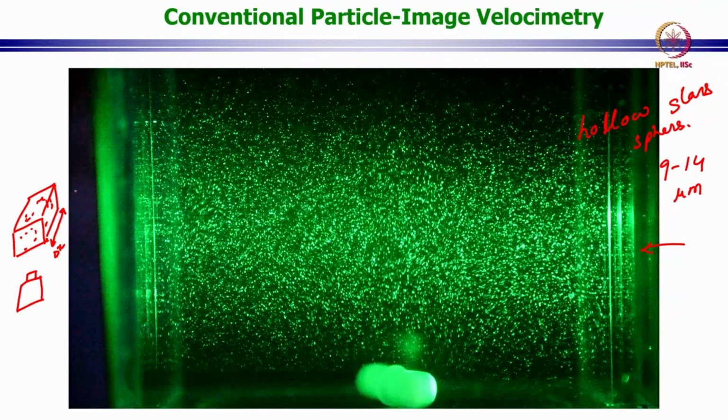So here what happens is, as the laser comes in and encounters a cylindrical lens, I'm not drawing the lens, it fans out and becomes a laser sheet, and only illuminates a small gap along the focal plane, and that's how you can image a particular focal plane without having to see the particles that are far away from the focal plane. So it makes sure that you encounter very low noise due to particles that are out of the focal plane. Now, in micro PIV,